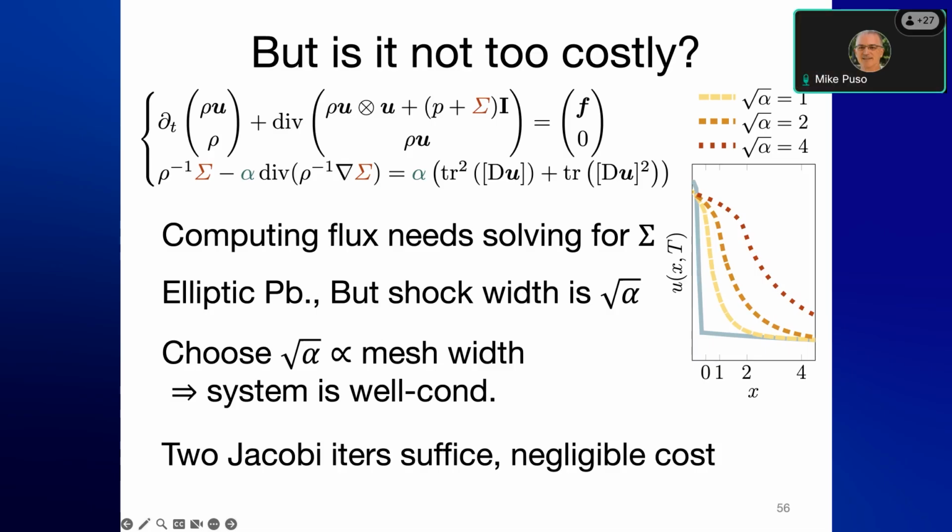And if you introduce viscosity into this, it doesn't hurt anything. Probably just helps. Would that be safe to say? Yes, if it's physical viscosity, then it only helps. The only thing is that if it is too large, you might need to use some splitting scheme because of CFL conditions.